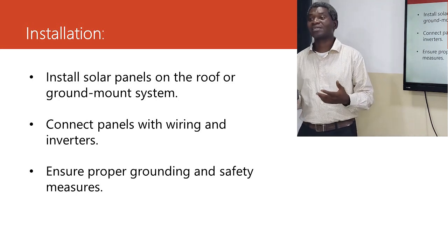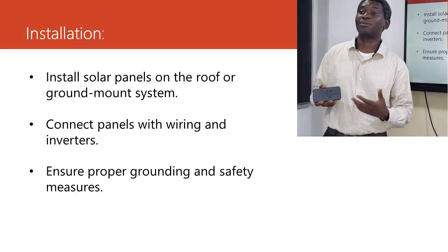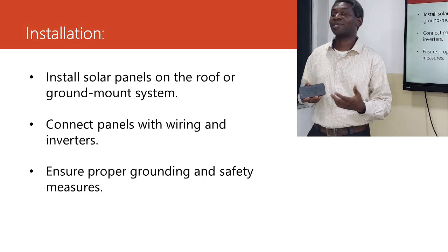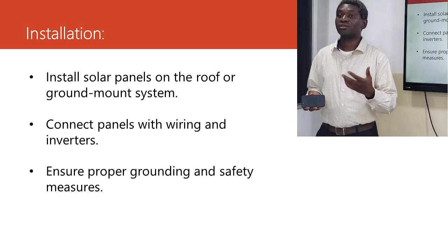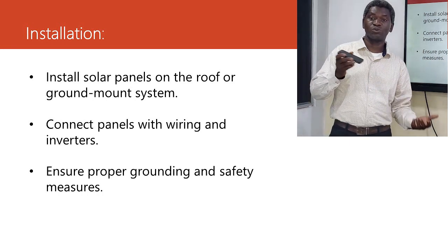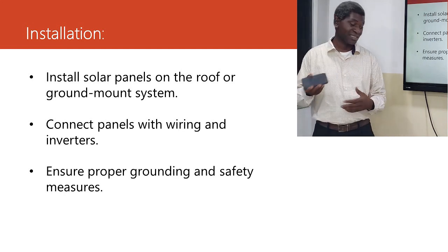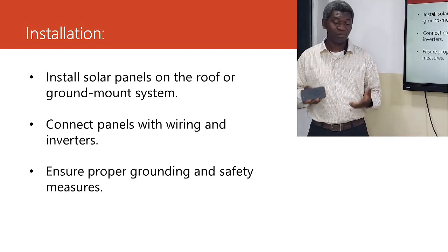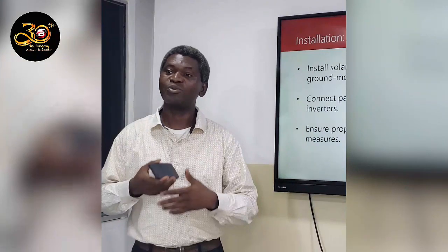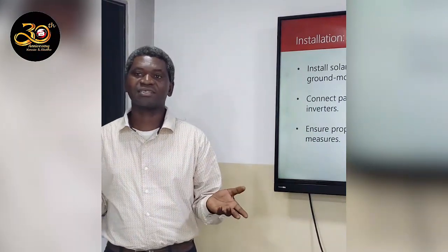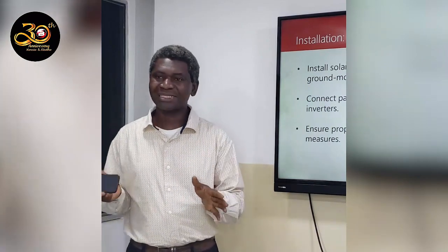Some solar panels are designed with automatic rotation, so as the sun is moving, the panel is also moving. So those are different. There are different types of installation. However, most of the installation we'll be doing will be just normal static installation. It doesn't have to move, so we always face it to the south. Maximize the places where you can get sun better.